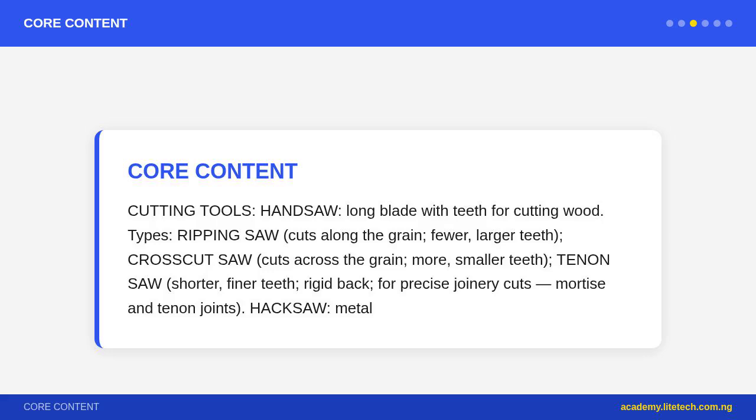Drilling and boring tools. Hand drill, or wheel brace, turns a drill bit by hand using a wheel mechanism, for wood and soft materials. Brace, a hand brace, a U-shaped frame that turns an auger bit in a sweeping arc, bores large holes in wood. Bradawl, a small pointed tool, makes starting holes, pilot holes, for screws in wood to prevent splitting.